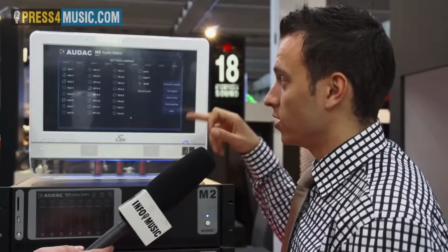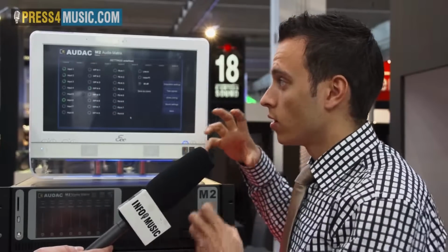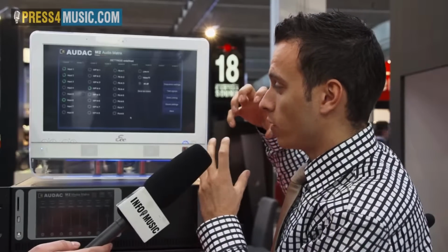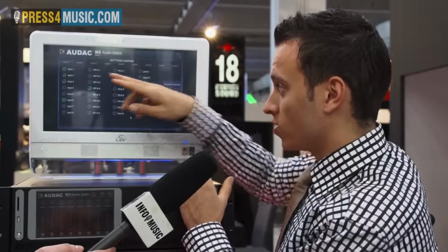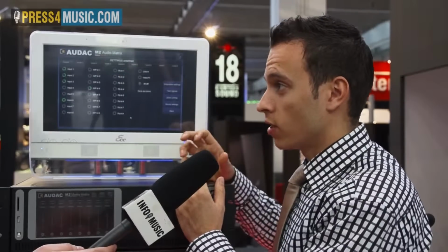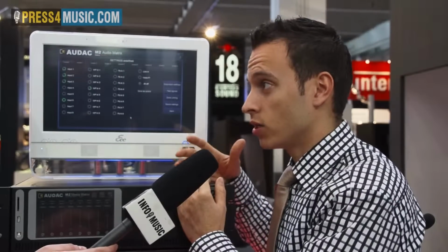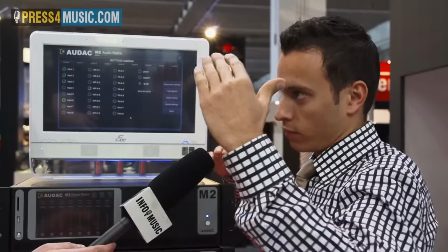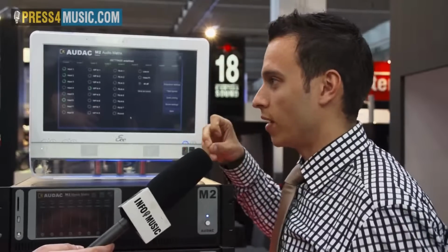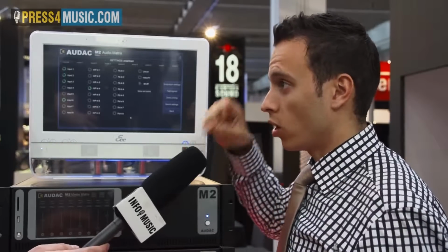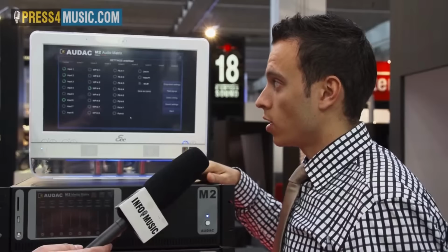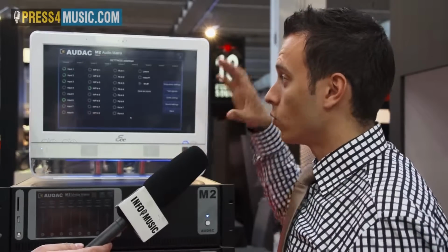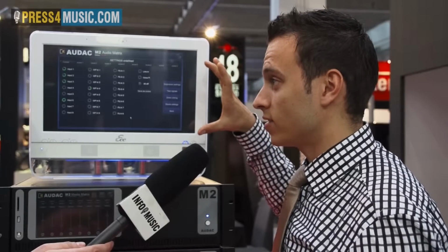And then we can set scenes, so we can set up to 8 scenes inside as well. To give you an example, if we have a meeting room for this output, we can set a scene for conferencing, a scene for presentation, a scene for entertainment. So the microphone levels will completely vary, and we could do 5 band EQ settings on all inputs, 5 band EQ parametric settings on all outputs, and then we have a central global 8 scenes as well.